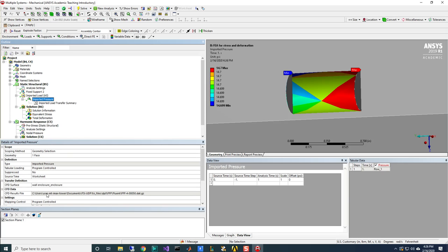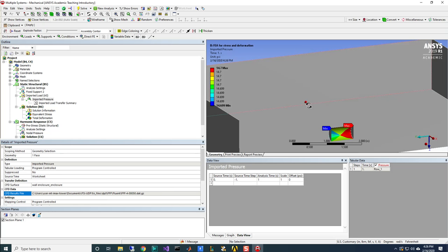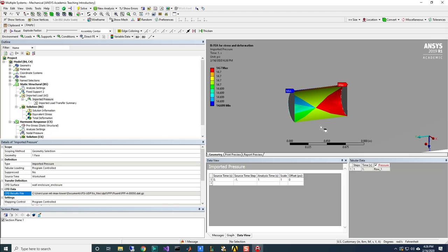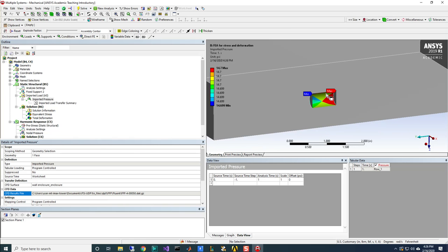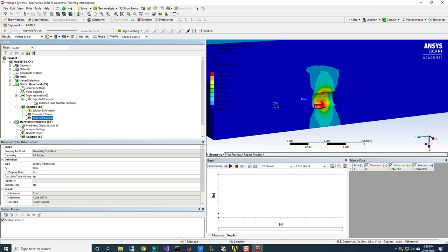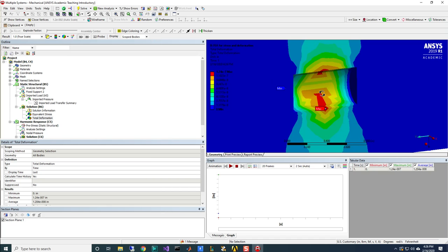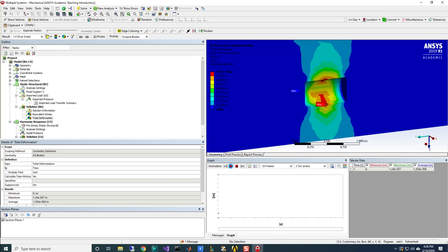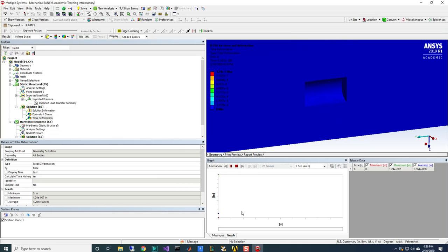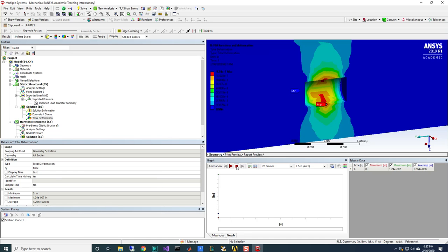Go into my default domain, switch my material to water, turn off heat transfer. I'll leave the turbulence model as K epsilon, it's fine here. Do not need to specify any domain initialization. CFX will figure that out from the boundary conditions. And for my boundary conditions, I have my inlet. Notice I named my boundary condition inlet to match the name selection from the meshing application. It's found that and automatically filled in my